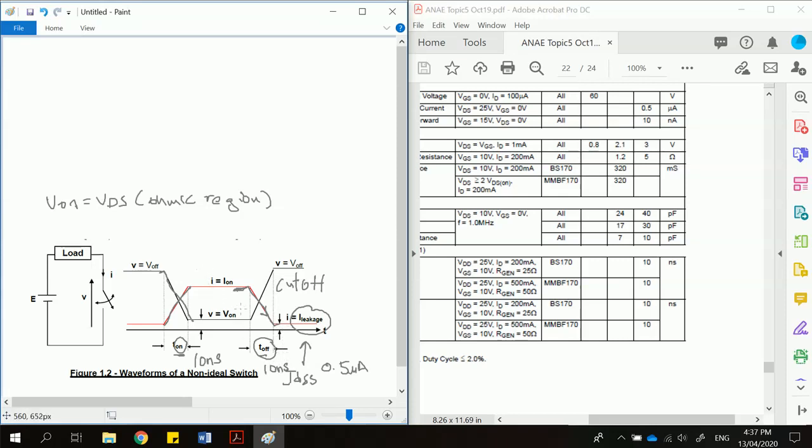Students, let's also take note that the reason why the voltage rises during the switch off is because this voltage is referring to the voltage across the switch. It is not a voltage across the load, but across the switch.